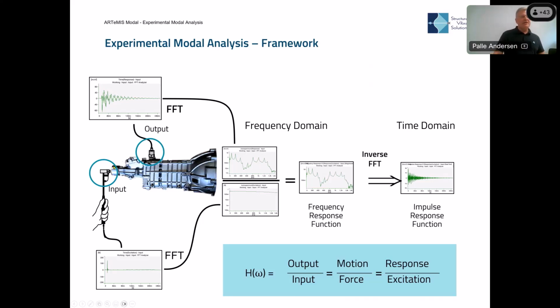At the same time we are measuring the response in the accelerometers. Here we filter this impulse through the structure, and the structure will then vibrate for a time. After some time, this vibration will die out. So we have a kind of free decay here, a transient behavior of the structure. And we are then recording this.